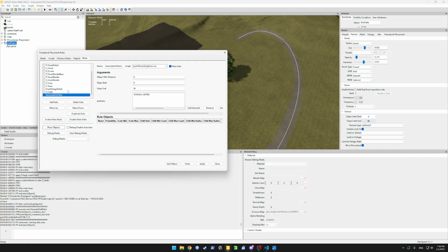So we'll need to create a new road mask based on this paint and remove it from the other one. Now, we added the generate dirt paths with the paint terrain by spline. Paint terrain by spline behaves strangely as it's executed before all other stuff is executed. So even if I add it at the bottom, but I do generate all the other stuff, it will override my textures, and I'll show you that, but we'll have to wait. So the idea is we just paint on one layer, then we can export the texture layer and re-import it as a mask, and so we will have generated a road mask just by painting it with the splines. We want that road mask because we can use it to remove it from our forest mask, for example.